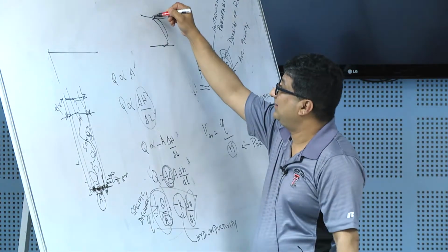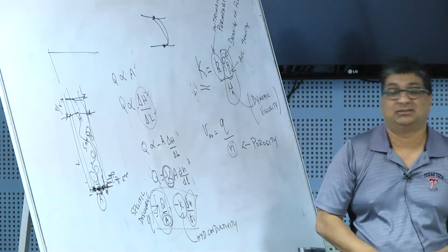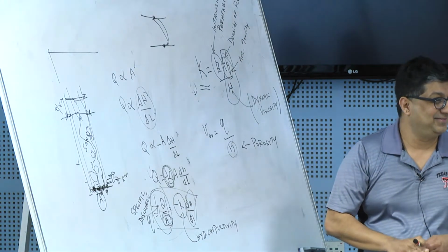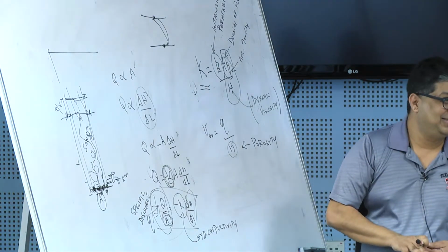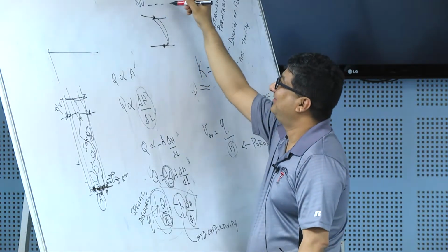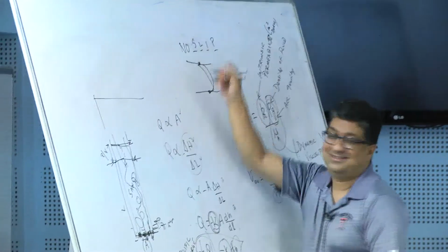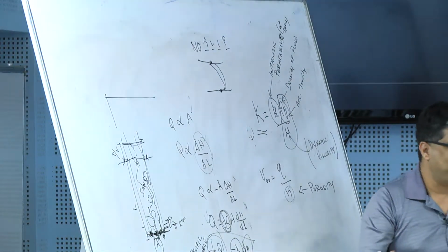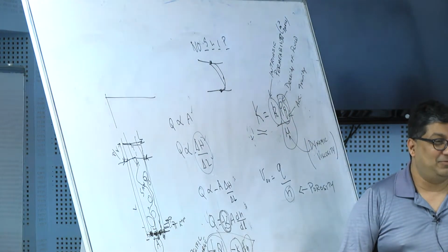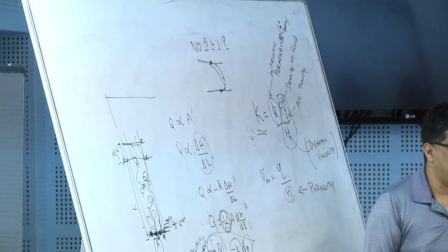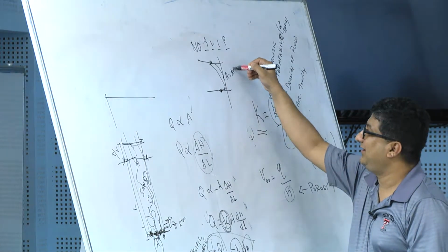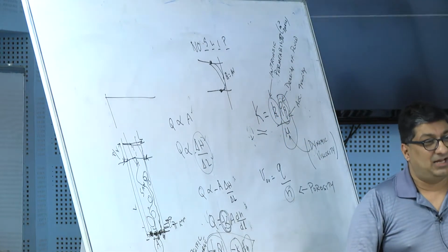Very similar to pipe flow, but a little bit more dramatic, because in a pipe flow, what's the velocity here? 0. Why? What's that condition called? So there's a no slip boundary condition there, which gives the velocity. The velocity is maximum here. Why? Because virtually there is no friction. It's surrounded by water. But if I take Q is equal to AV, I'm getting an average velocity through my pipe.